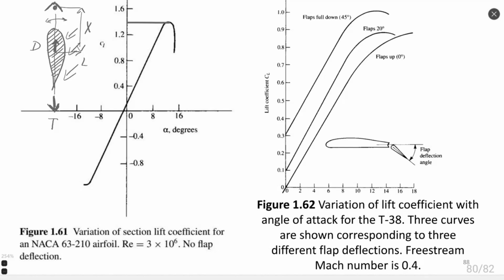Bigger is the rocket, smaller are the fins. You know, on small rockets, fins are big, but on big rockets there are no fins, especially on the rockets which have thrust vector control by engine. Okay, but for small rockets, fins are essential, and I think it's important to estimate two perpendicular forces: force of drag resisting to thrust, and force of lift that helps to control trajectory.